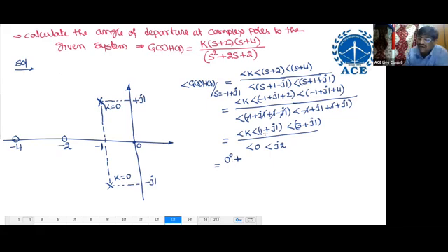Plus angles are added or subtracted. Angle of K 0. Angle of tan inverse of 1 by 1 means how much? 45 degrees. Imaginary part 1, real part 1. Tan inverse of imaginary part 1, real part 3, tan inverse 1 by 3 is, I think, 18.43 degrees. Divided by angle of 0, 0 degrees, plus angle of J2, 90 degrees.